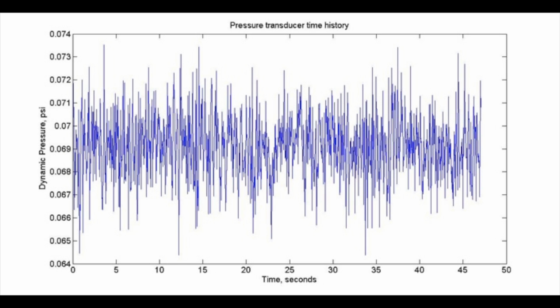Notice the noise picked up by the data acquisition system. What causes this is an unconditioned power source from either the sensor equipment or the data acquisition system. A frequency can be assumed by measuring the time difference from peak to peak, but not with enough accuracy to be able to guarantee the frequency.